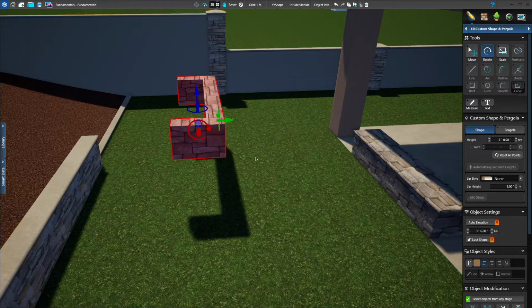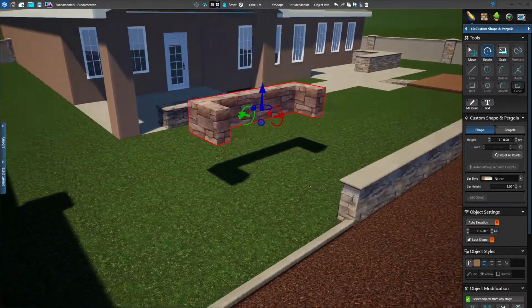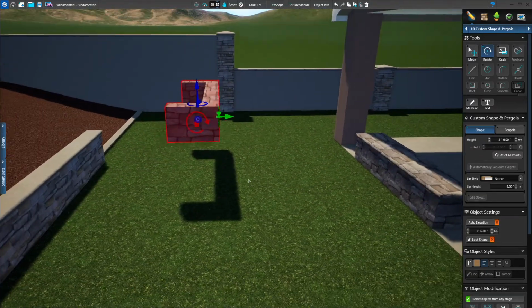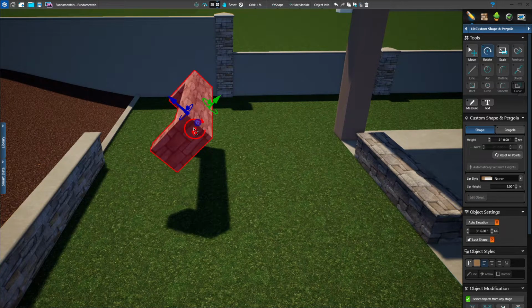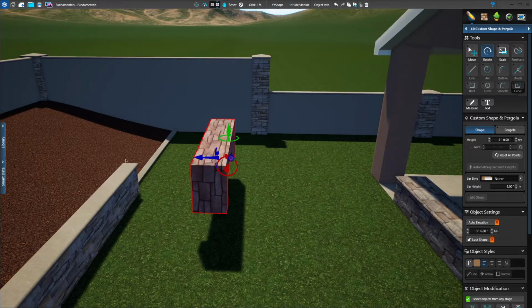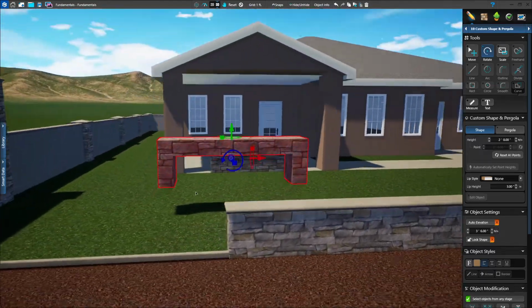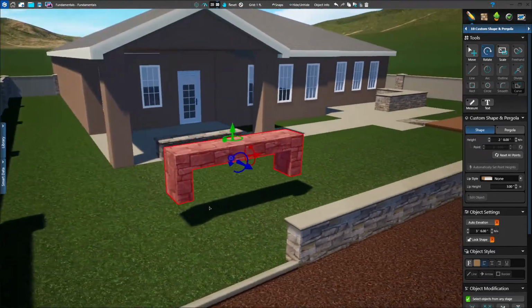I'm going to click on rotate. Now I've navigated my way so that I'm looking at this from a side perspective. That's helpful because it's the red arrow that's going to rotate this in the right direction. So how you rotate is take your cursor over the red arrow. See how it highlights a brighter color red? Hold down your left mouse button and move your mouse to the left. And that shape is going to rotate, and it snaps every 45 degrees. I'll just stop when I get to that vertical orientation.